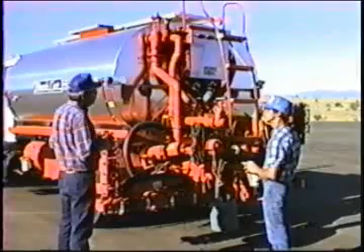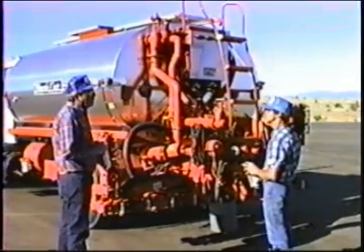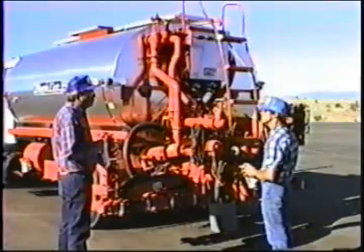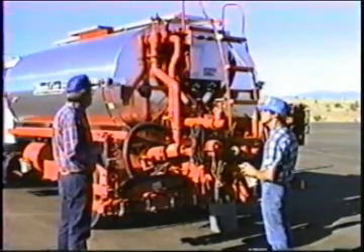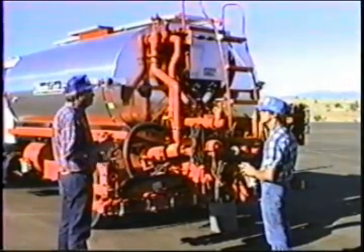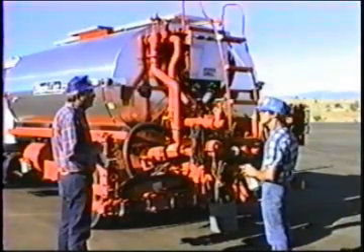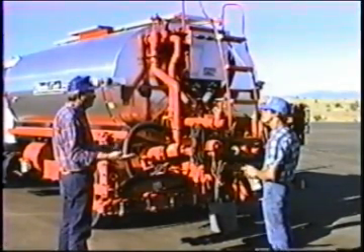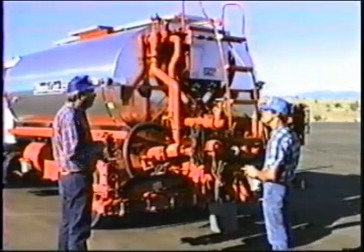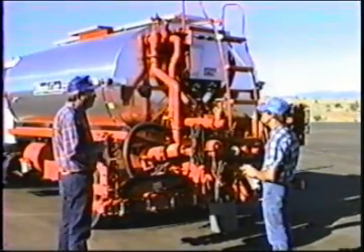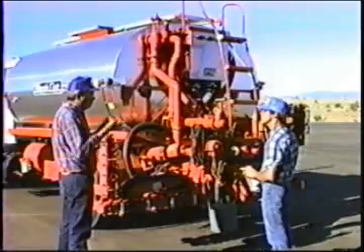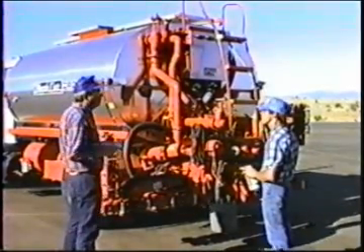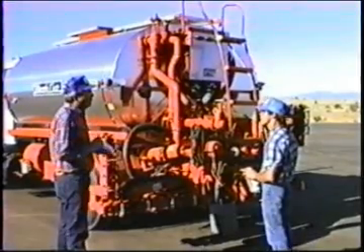First job is to load the tank. Put a little bit in it. I say no more than 25% of the volume of the tank. This is a 2,000 gallon tank, so put in no more than 500 gallons. That asphalt's on the bottom, the water's on the bottom. Drive it around, shake it around. That'll get the water boiled out of it while there's room for the steam in the tank. The steam can boil up through the low level of the asphalt and get on out of the tank.